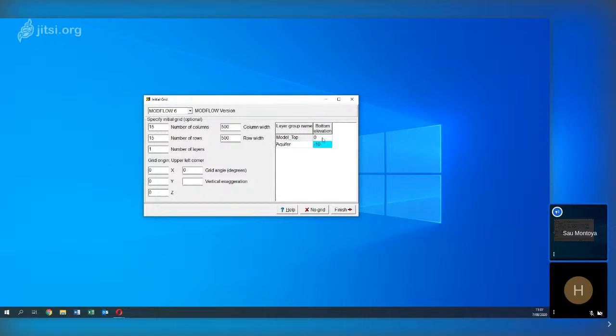And it will be from 0 to -10. That's all right. So please check this. Okay, we are working with a grid of 500 by 500 meter. I mean, in your local area, in 500 meters a lot can happen in groundwater. You can have wells, you can have drains, you can have contaminant sources, and so on.